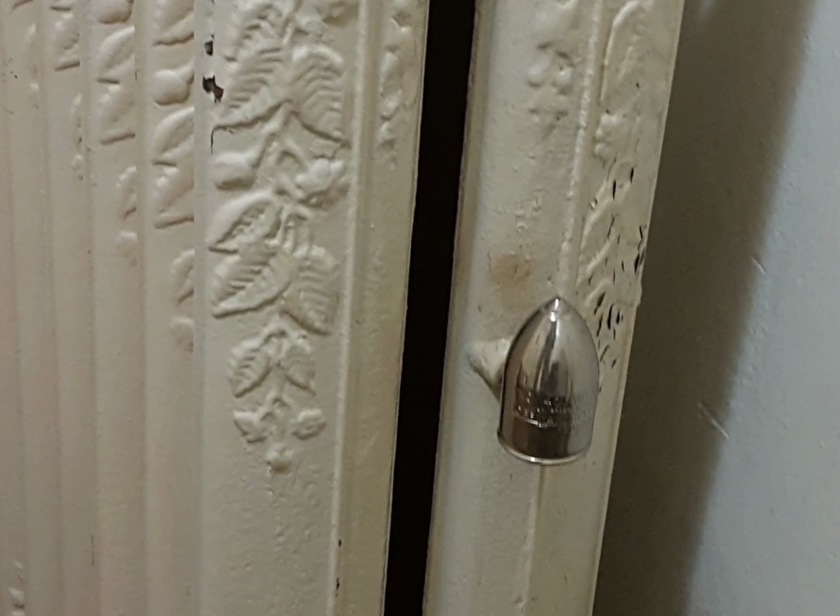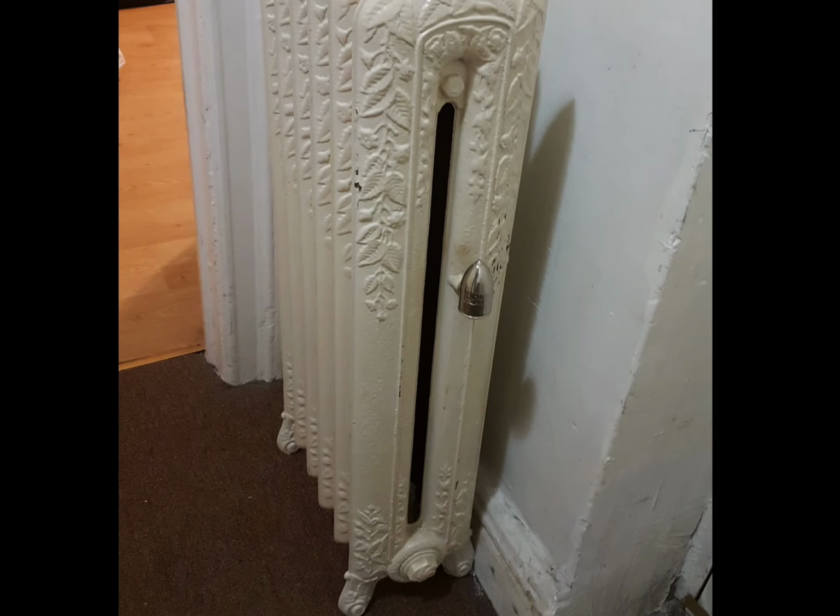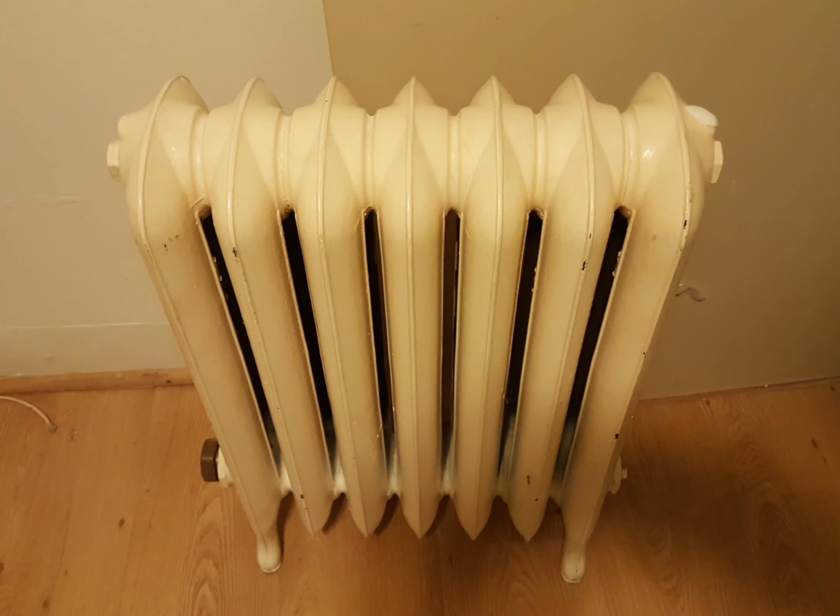As a matter of fact, when I was younger, in certain cases I would just take the vent off the radiator and this thing would blow out room temperature air for a good couple of minutes before steam would ever even get into the service valve. Now, with a cast iron boiler, I don't have to describe it, because chances are you probably wouldn't hear it, since they run at a much lower capacity.